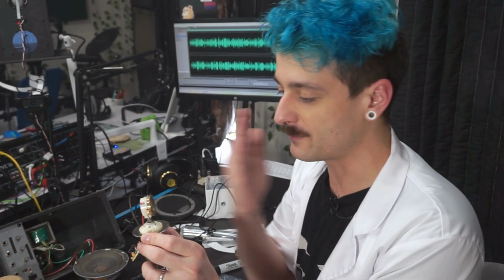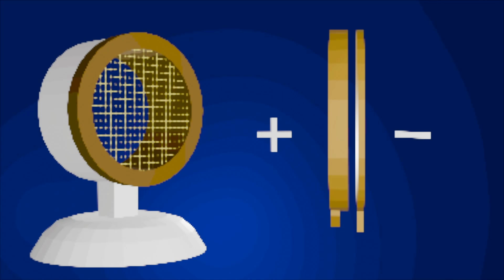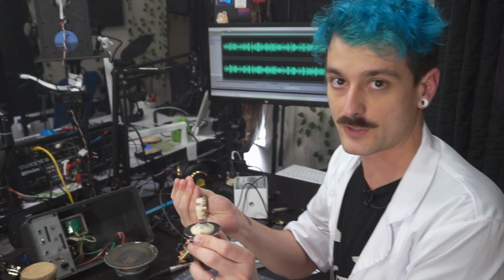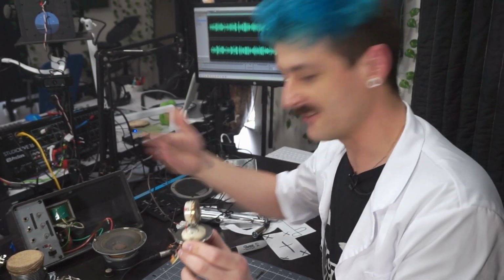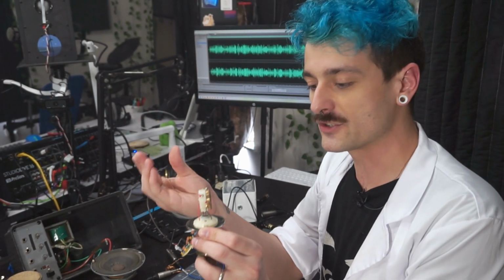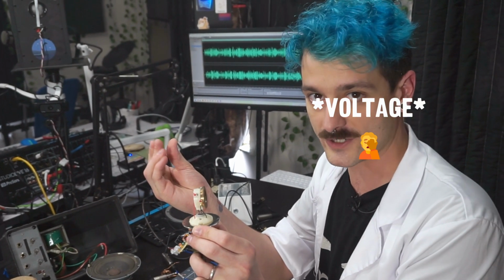When your sound waves hit the plate in front, it moves ever so slightly closer to the plate behind it, and that creates a change in its electrical capacitance. So instead of a coil moving past a magnet, we can kind of see how those charges between those two plates are fluctuating. Why would we do this, even though it's wildly more complicated?